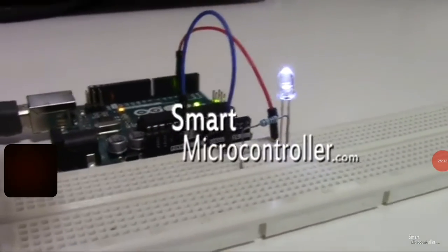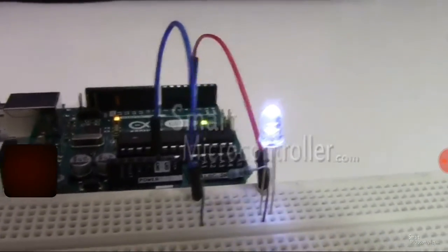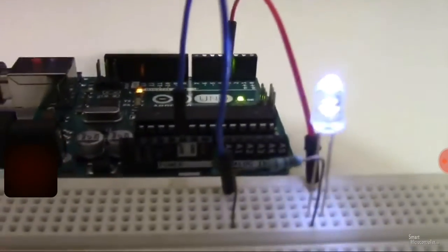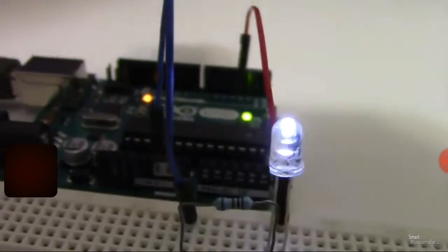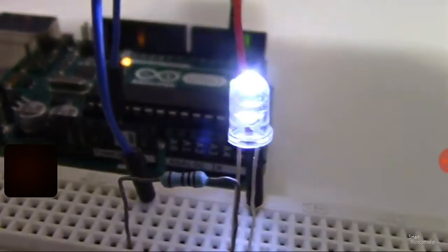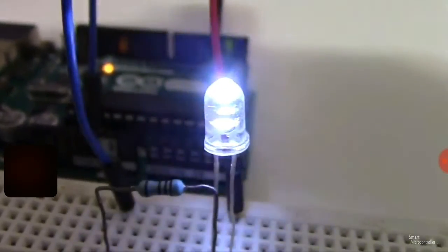In today's video, we look at using the pulse width modulator function of a microcontroller. The Arduino platform makes this function really easy to use by using the analog write function with an added variable. To demonstrate what the pulse width modulator is used for, we connect up an LED and vary its brightness using this function. It's quite simple to get going, so let's start building.